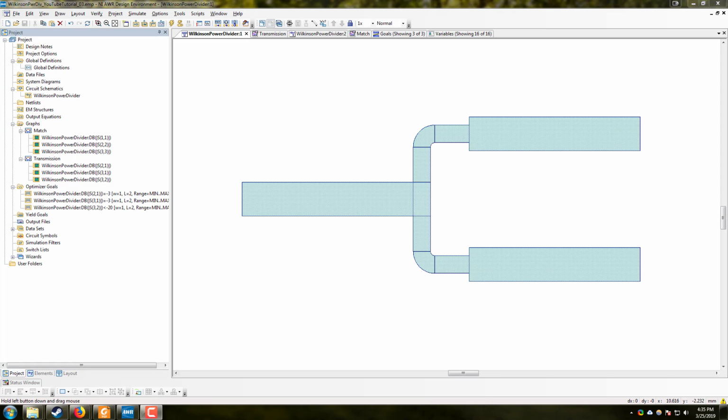And this means that, for example, our resistor might be a few millimeters long. However, the wavelength is many meters long. And as a result, as far as the signal is concerned, that component looks like one solid block. And so we make all these equations, we make all these assumptions when we use our basic theory, and this gives us the base that we build upon.